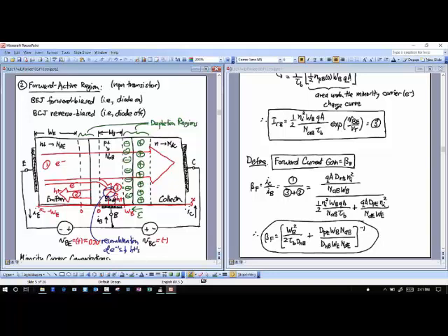Yes? The tau variable for the carrier lifetime, is that a property that's given, or is it something calculated? That's something that's usually measured, so I'll say given, yeah. You could try to calculate it, but there's physics that say what it is. That's based on the capture cross-section of your atoms and that sort of thing, which really comes down to the physics of the atoms, like where the valence shell is. So you could try to calculate that, but in general, people will measure it and you'll use those measured numbers. Calculated theoretical numbers get close to that. Okay, you'll be given that, is the short answer.